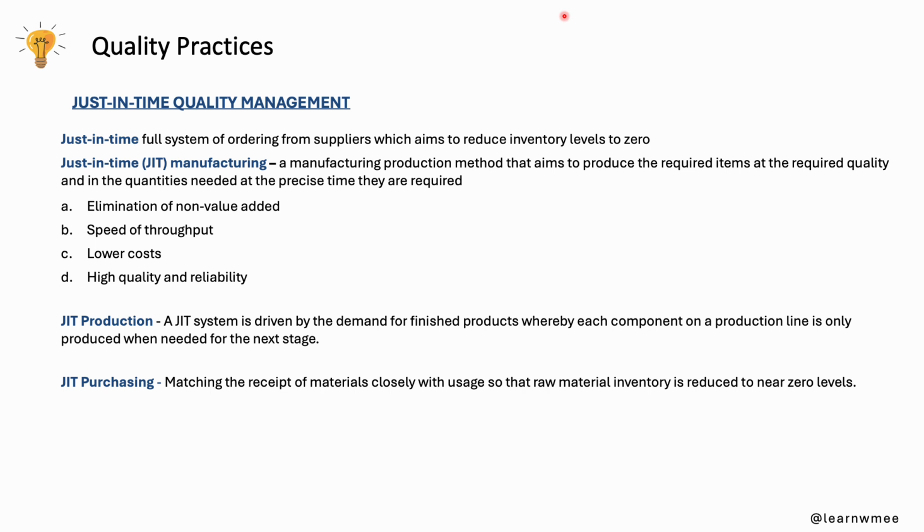Traditionally, manufacturing was performed in large batches to reduce the cost of setups. These costs were incurred because it was necessary to set up the machines differently to produce various products. The problem with large batch sizes is that it leads to delays and large inventory. In the just-in-time approach, the aim is to have batch sizes of one by having machines that do not need to be continually set up for different products. This can be assisted by cell-based manufacturing. Having a batch size of only one can also save costs, and the producer will be more responsive to changes in customer demand.